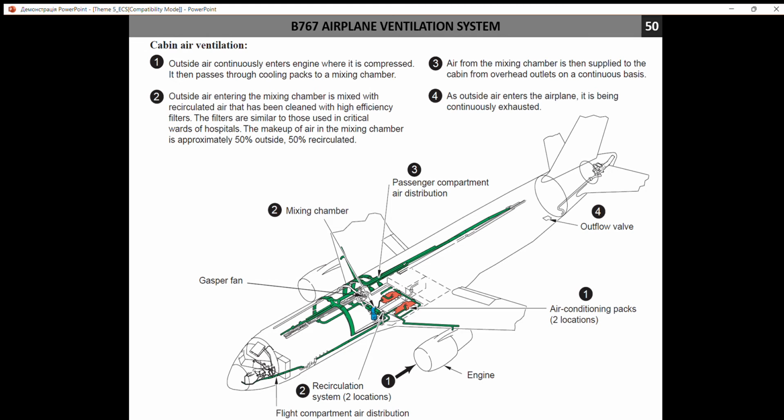To save some air, bleed air, because bleed air is air that is taken from the compressor, so we take this air for the purposes of passengers, for the people on board, and we take a part of engine thrust in this way, and we need to burn fuel for the purposes of passengers. So that's why you may find an air circulation system in some airplanes.